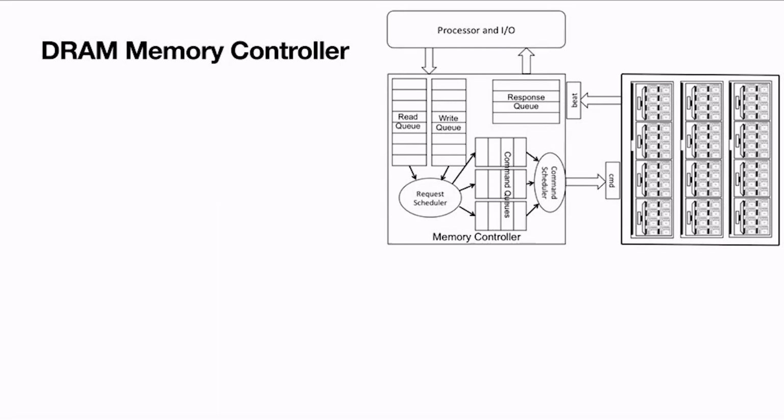Because the processor, when there is an LLC miss, says, okay, load the data from this address. But the DIMM cannot understand that. For that, we have to convert this load request into commands like, read the data from this particular location. That is nothing but you first pre-charge this particular location, activate this particular row, and then read a column from that particular row. That is what we have to give. That means this load command is now converted into pre, act and cache commands. That is the request to command conversion.